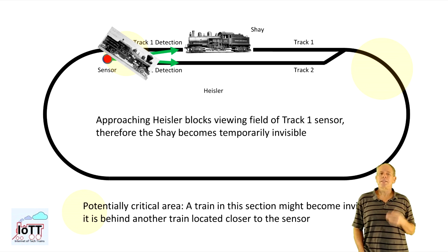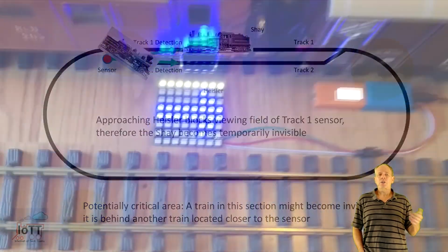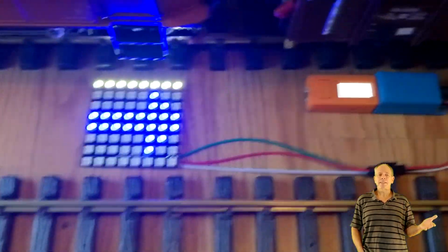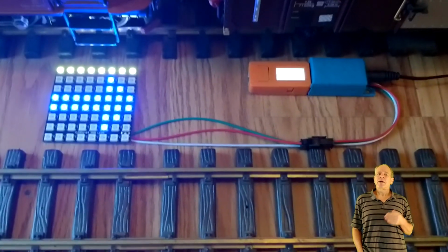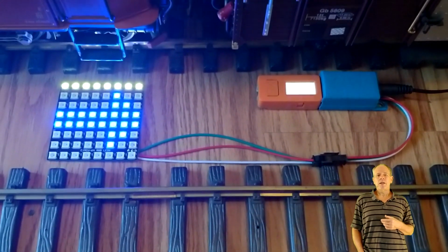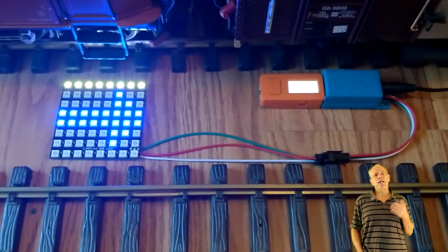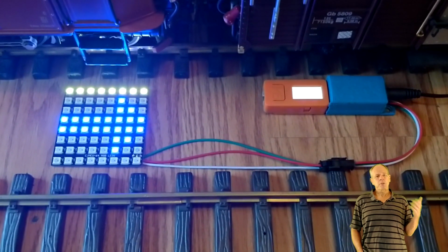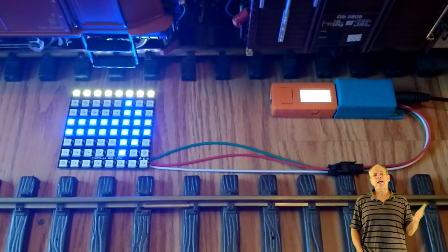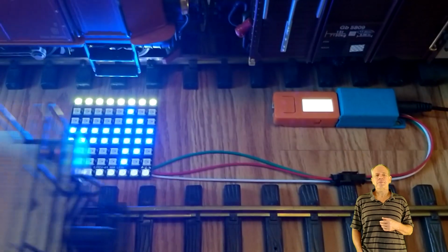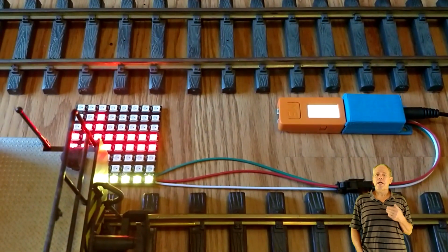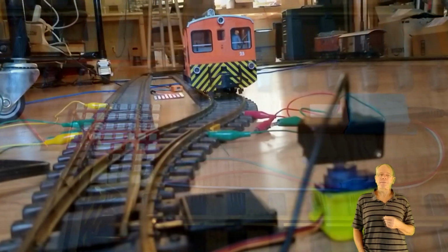Since occupancy is defined by minimum and maximum values, it shows unoccupied when the measurement is less than the specified minimum. This could potentially be a problem, but not in this application as long as the correct status comes back before the train in track 2 is detected. This is clearly the case here based on the geometry and location of the distance sensor.